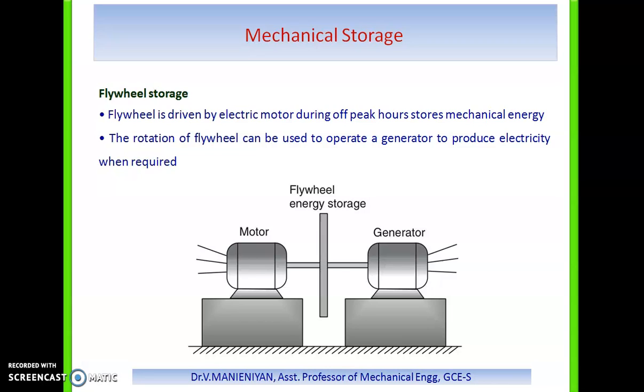The basic idea of flywheel energy storage, sometimes referred to as a super flywheel, is to accelerate a physically designed rotor to a very high speed in a vacuum using electric motors, so that a high stored energy density is achieved. The energy is stored as kinetic energy, most of which can be electrically regained when the flywheel runs as a generator.